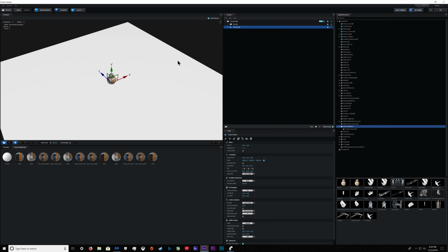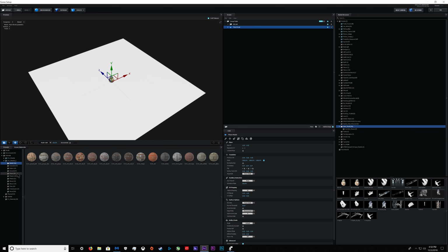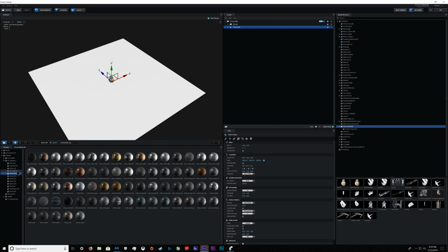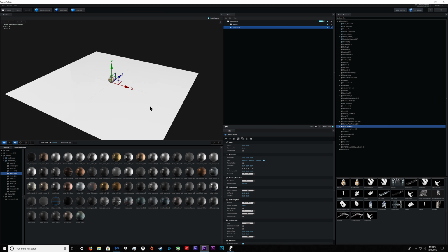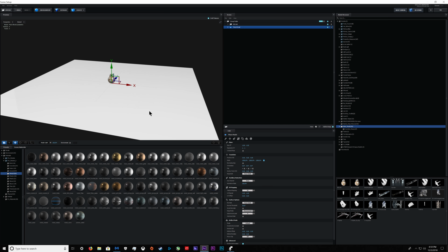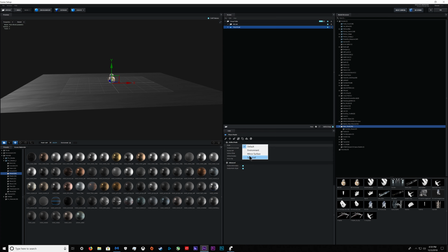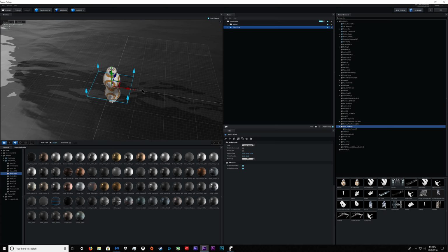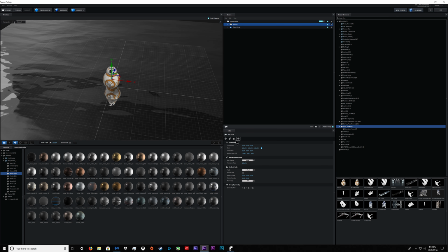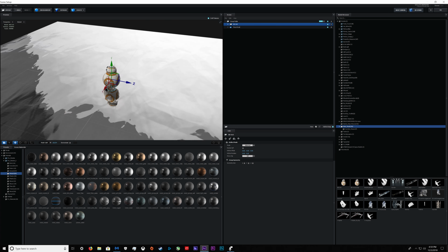First thing we're going to do is just find a texture that reflects nicely. I'm going to use Pro Shaders 2, Metal, and then I'm probably just going to do exactly what I did last time and use foil. And then down here, have the plane selected, click Reflections, this little square box right here, and you want to change the mode to Mirror Surface. Now you get BB-8's reflection. And then for BB-8, we're going to do the same thing, but we're going to choose Spherical, since BB-8 is a sphere. Now he gets Spherical reflection.